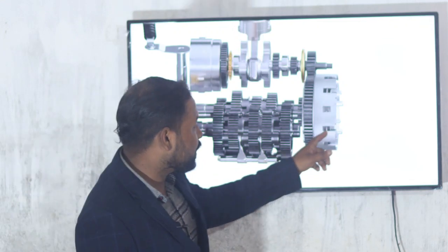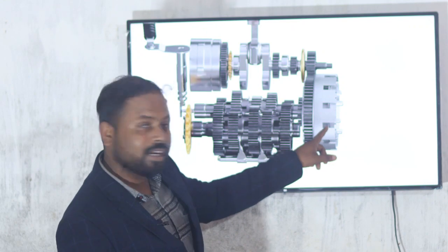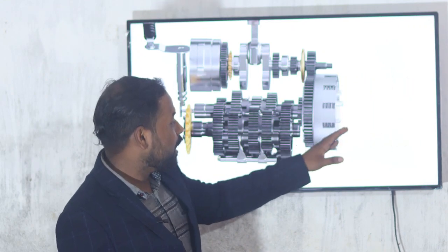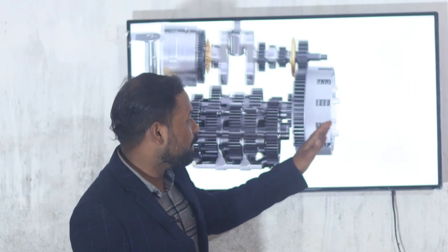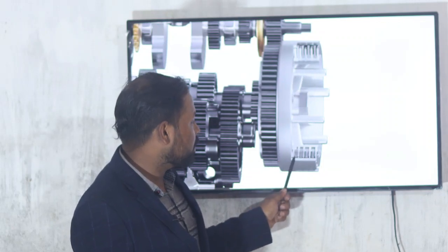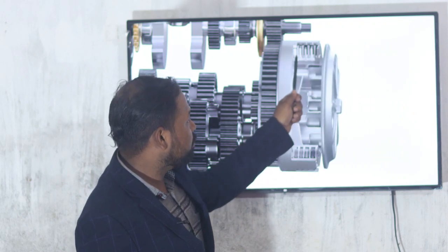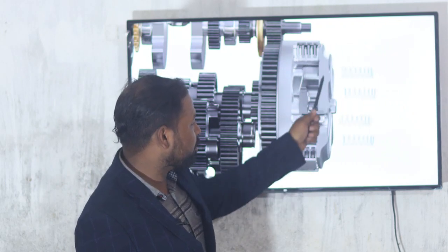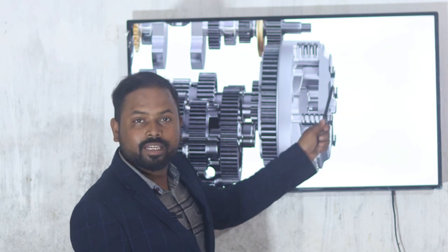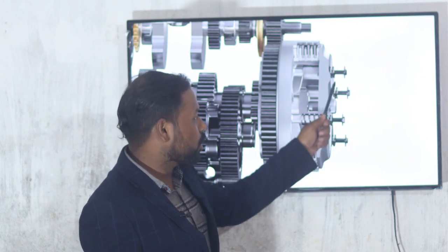Here both are disengaged. Before it is engaged, and now when it is engaged, see, both are engaged and the multiple clutch plates are now engaged. One is the steel plate and another is the clutch plate. Here you can see the different plates, and this is called the pressure plate, and here the pressure springs are mounted, then nuts are mounted.